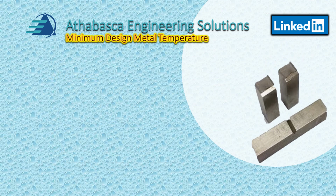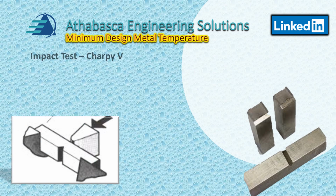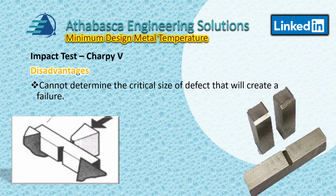But there are disadvantages for the impact tests. They cannot determine the actual critical size of a defect that would create the failure. There are other tests to assess that, and there's API 579, the crack assessments as well.